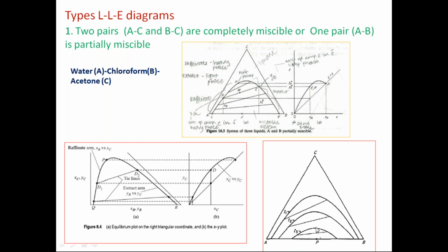you will have a very small binodal curve. That means the heterogeneous area decreases when the temperature increases. At lower temperature you can see more heterogeneous area. At high temperature you have very little heterogeneous area, whereas the homogeneous area is very high. All these compositions above this curve show only a homogeneous phase. We require a heterogeneous phase. Therefore high temperatures are not suggestible for liquid extraction. You can do it at low temperatures.